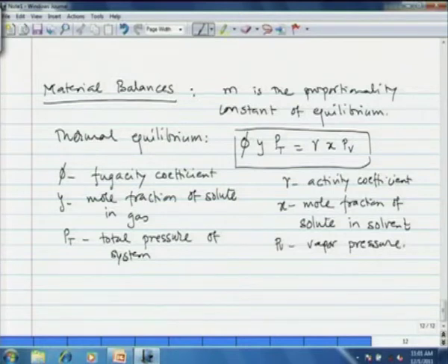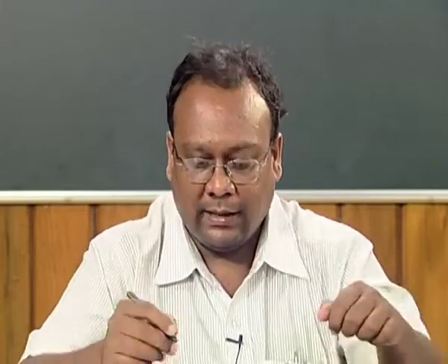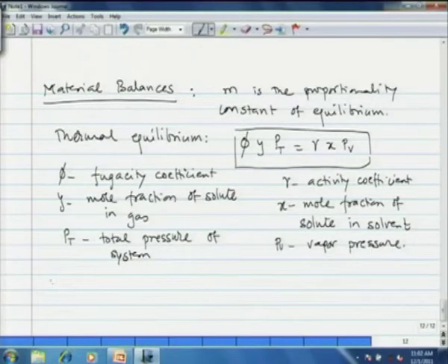Now, in the present situation, the total pressure of the absorber is close to atmospheric. Okay. We have acetone in very dilute concentration, only 10.3 mole per hour in 687 moles per hour of air, and therefore, we can neglect phi. So, phi can be assumed to be 1.